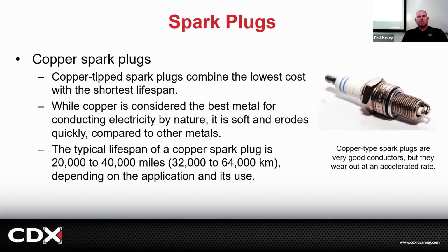I wouldn't go iridium on that because you're going to need to change your coil and your wires and all that stuff, and your cap and rotor, before the spark plugs are due. You're going to leave the spark plugs in there. It doesn't make sense. But if it's a new car, right?